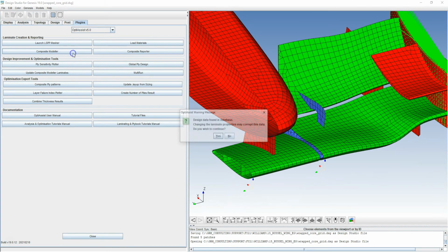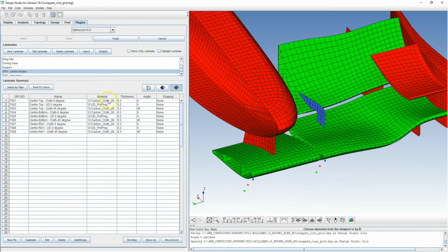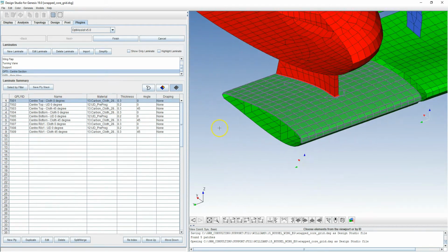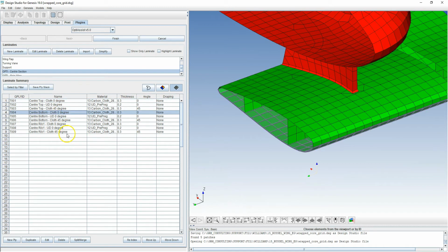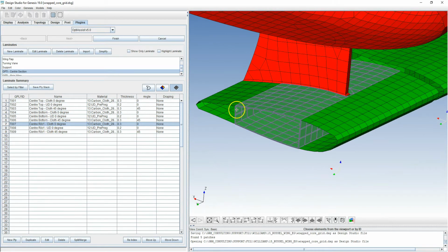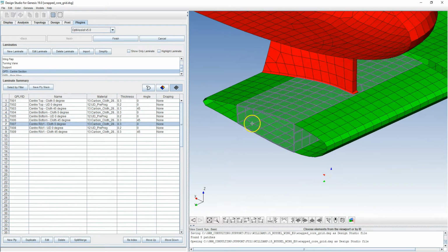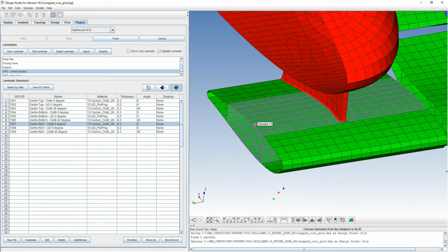So if we take a look at this laminate here, this is one of our tutorials. So we have some candidate plies on the top surface, on the bottom surface, and then in this variation of the tutorial we have a core or a central section that is a wrapped section. So what we want to be able to do here is just simply make the splitting a split along the y direction of the wing.